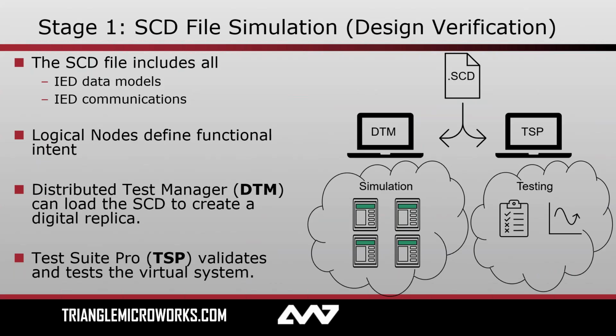So the SCD file, or system configuration description file, contains all the IEDs that will be in my substation or system. It contains the data models for those IEDs. It documents the communications which will be happening, the signal exchange back and forth between those different IEDs.